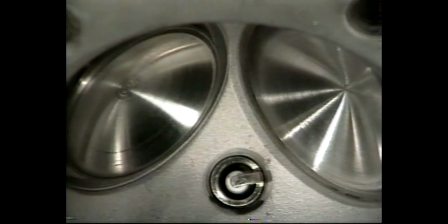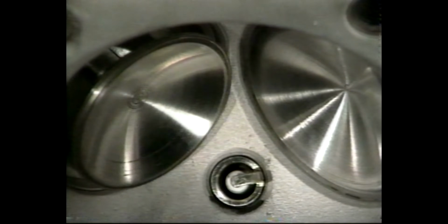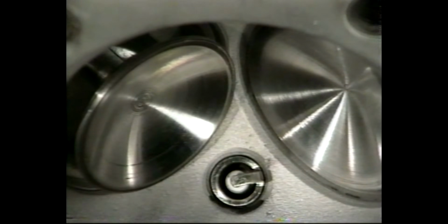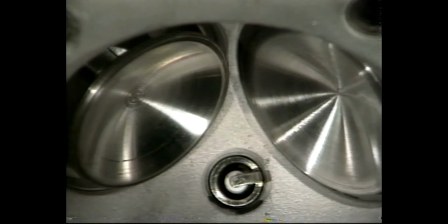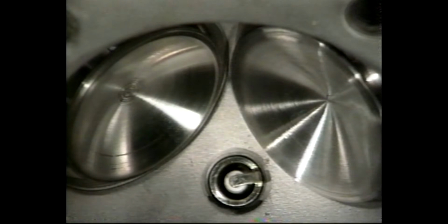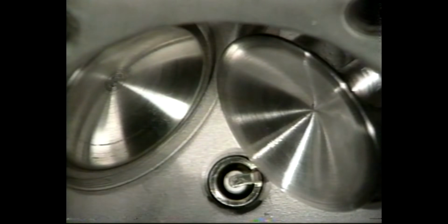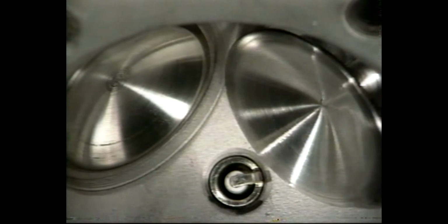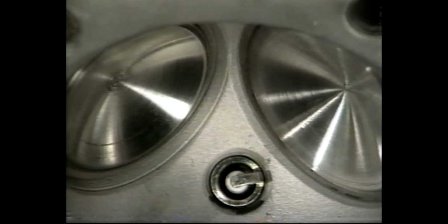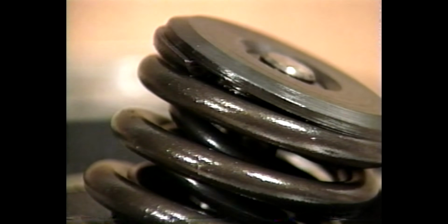Increasing the cam lobe and valve lift will generate more horsepower and torque by simply allowing more fuel-air mixture into the cylinder without compromising our power at low RPMs. Ideally, to take full advantage of our valve lift, the valve would have to open almost instantaneously. Unfortunately, this is not possible due to a couple of factors, one being valve spring failure.